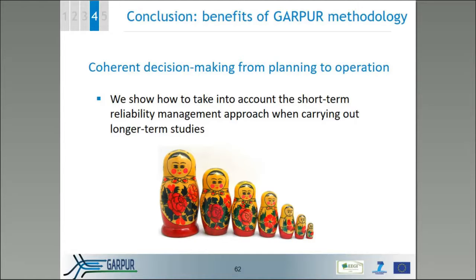Nevertheless, what you can do is see how the system would be operated in real time along a set of possible trajectories for the next day, trajectories which are then sampled according to the uncertainty that you have about these factors. And for each one of these trajectories, you should basically look at what would be the response of real-time operation in terms of reliability management, and see whether or not it would lead to a problematic situation where the residual risk would be too high, or the probability of unacceptable system response would be too high. And then this allows you to assess day ahead different candidate decisions that you can take in terms of the implied risk on operation.